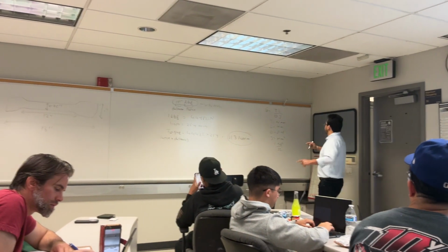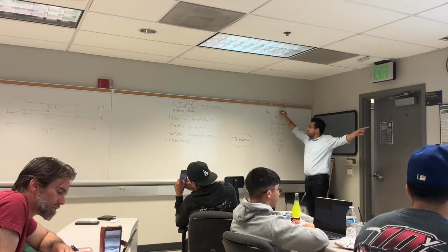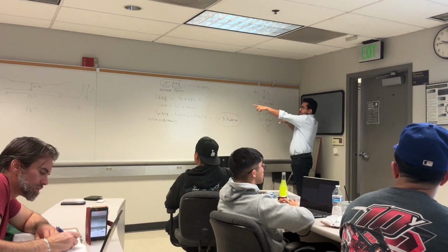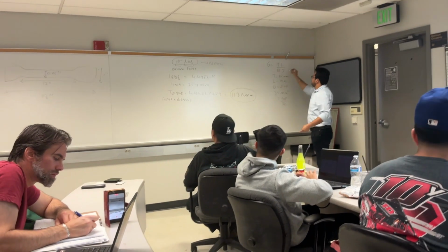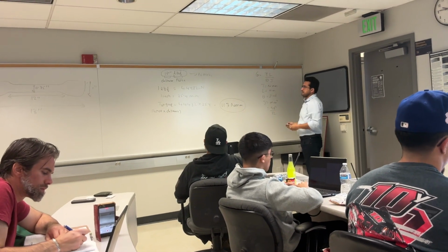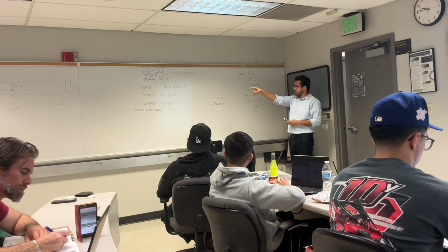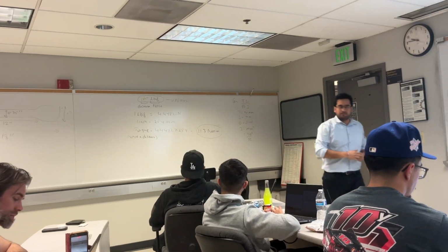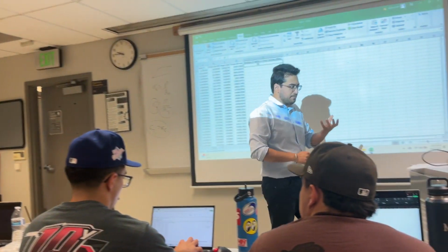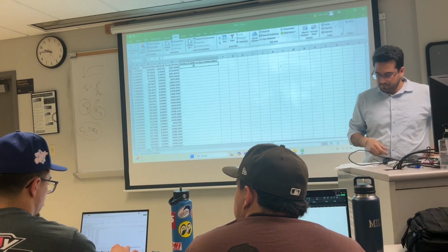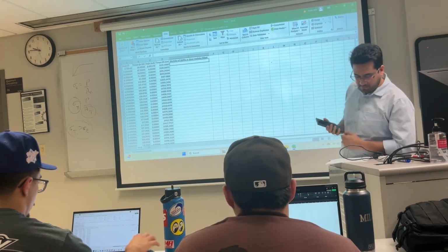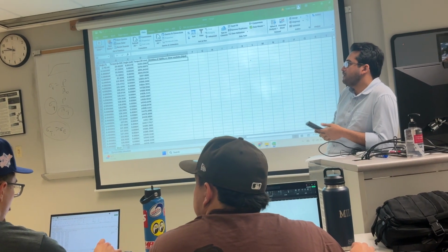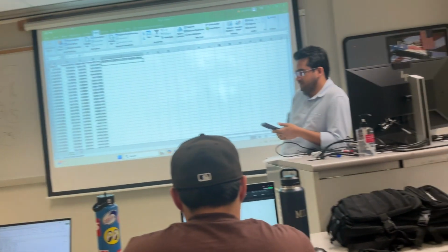Torque you have, you calculated, right? Torque column, theta column, L from the standard is a constant, J is also from the standard, like you need D, right? Pi d to the fourth by 32. Solve this in mm. So converting, solve it all in mm. Give me the final J.